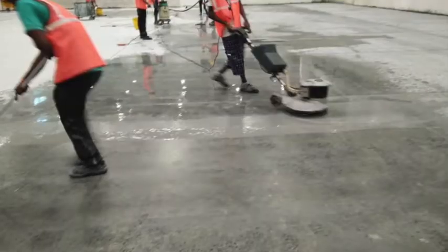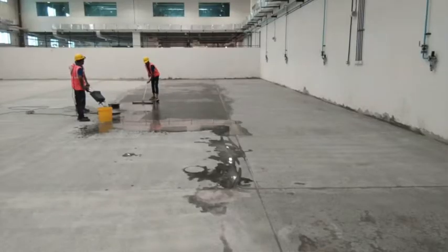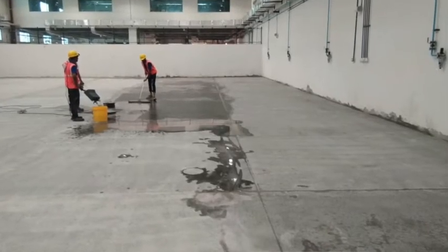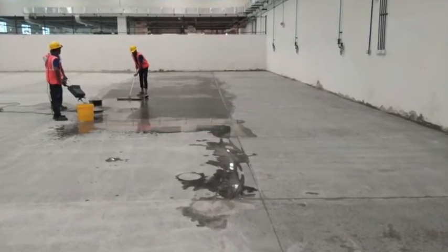Now, the second important point, which is quite practical, is that the floor must be washed and let to dry before you apply the densifier. Because the densifier has to penetrate into the floor, into the substrate. If you have a lot of dust, a lot of slurry, a lot of leftover material from previous grinding steps, your densifier is not going to really go into the floor. So this is again very simple, but a very, very crucial step.